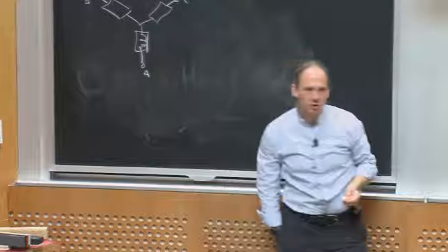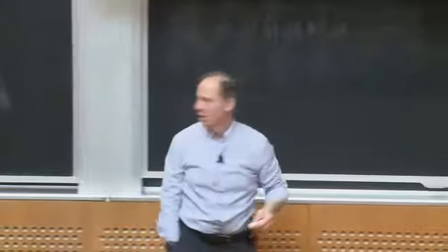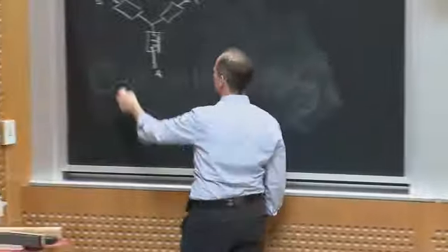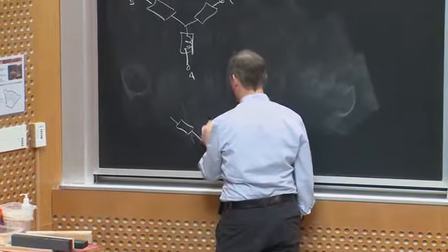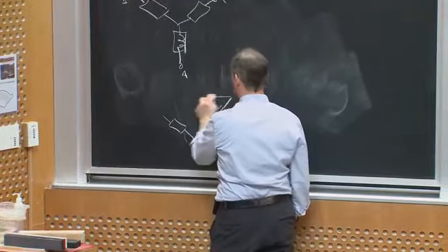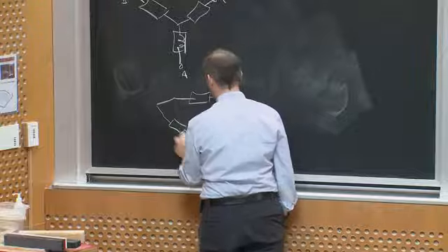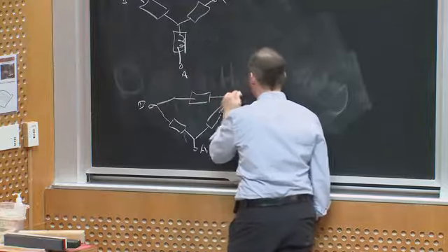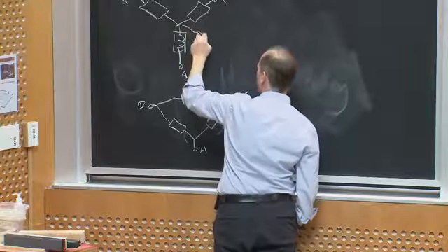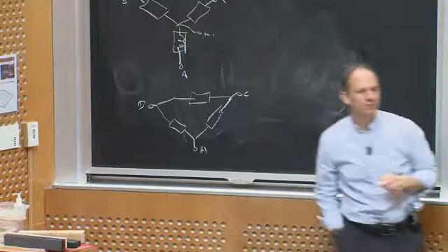I only have 3 terminals, okay? Or maybe I have a delta connection where the machine is wound like this. And again, I have A, B, and C. In the Y case, I might have a neutral. In the delta case, I have no neutral, okay?